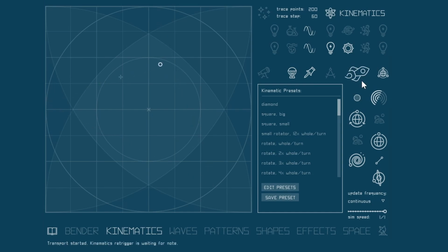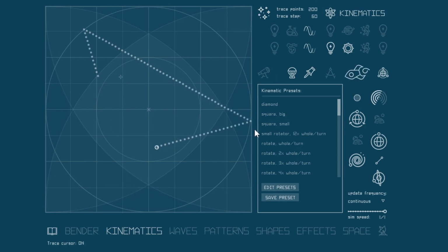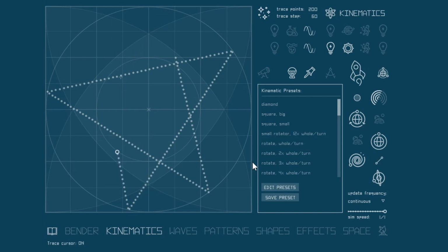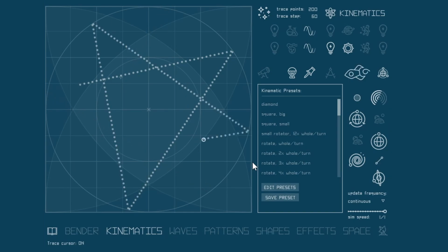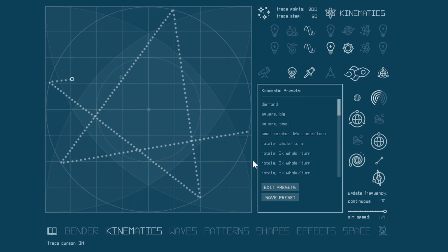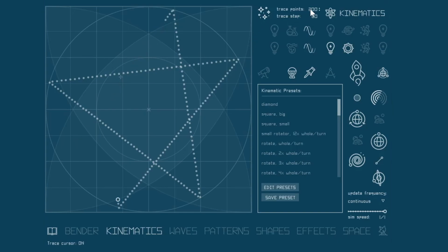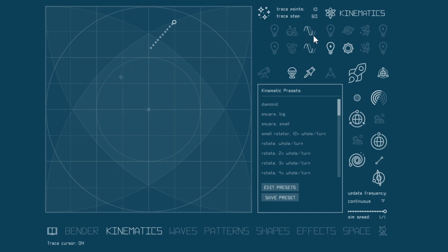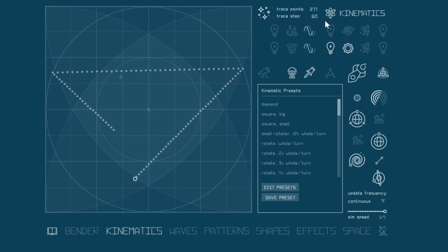A digression here. Switch star map button to visualize cursor path. Each point in the path is a contact interface object, and there is limited number of those, so the visualization has limited number of dots. And it looks a bit like a comet tail. You can adjust tail length by defining number of trail points. And adjust point spacing by defining trace step.